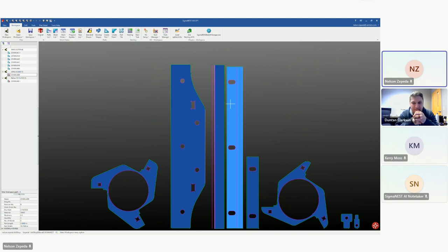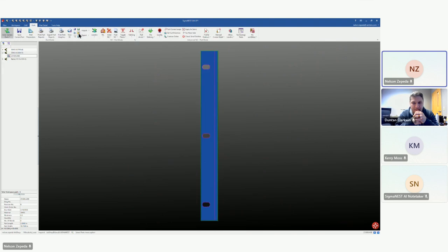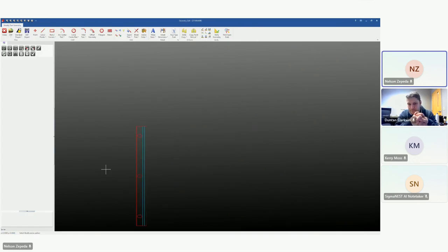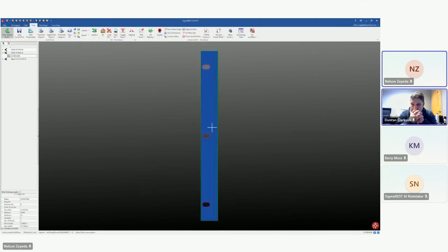And like I said, for this one, my cleanup would be fairly easy. I can come into our geometry edit, and I could do this a couple of different ways. I could either just delete the lines completely, or maybe you still want them there for reference. I can just set them to no cut. And we'll just do no cut there. Okay. And then now it's good to go. I still have it up for my drawing or any reports, but we're not going to do any kind of laser or etching or cutting on that now. So they'll be ignored for that process.